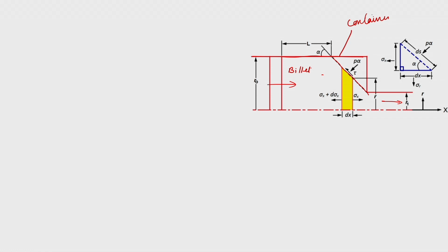We are assuming a cylindrical portion of the deforming body, because in most cases the container is cylindrical in shape. The frictional force between the container and the billet will be experienced at this length, because this is the part which is moving forward from the ram, pressing this billet here. This is the length where the billet is in contact with the container, the overhang length L.